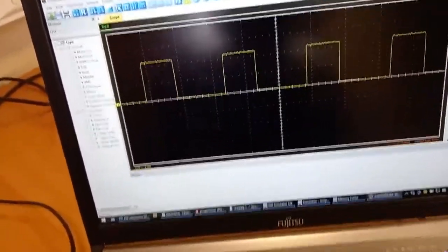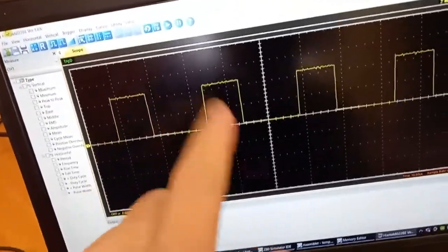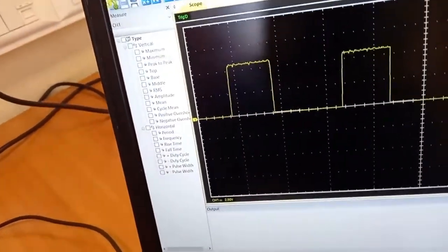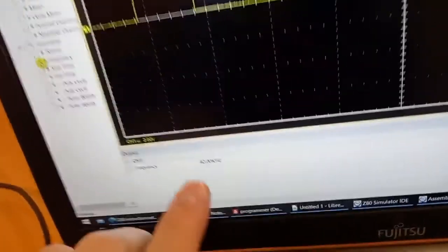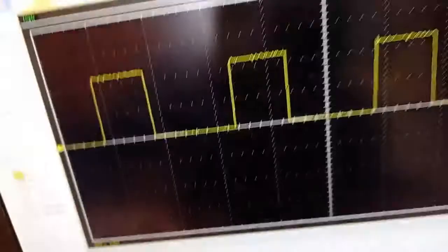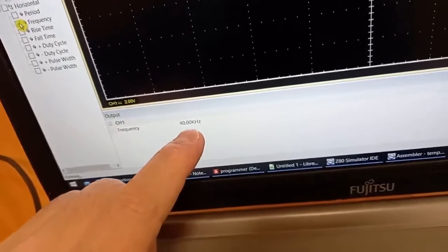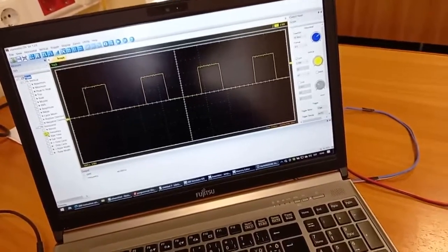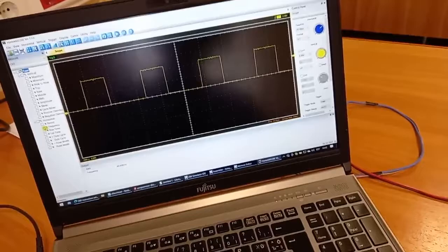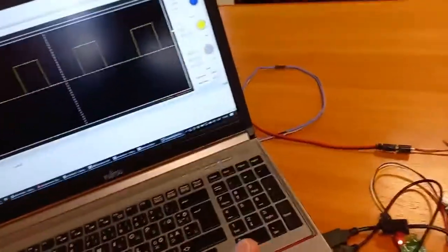So we have this beautiful thing, but the problem is that it's too fast. The pulses come too fast, we are not able to hear them, because the frequency is 40 kilohertz. That's 40,000 jumps each second. That's too much. We cannot hear it with our ear. Our hearable frequency is, as you remember, from 20 hertz to 20 kilohertz, but it's 40 kilohertz. So we need to delay the CPU.